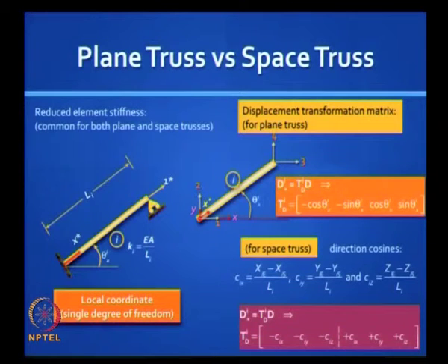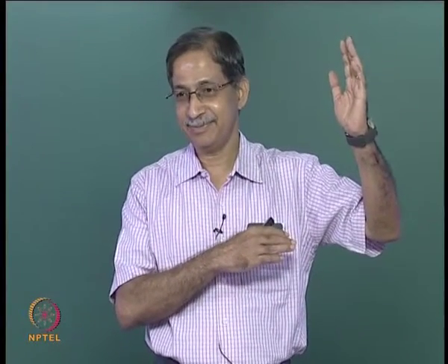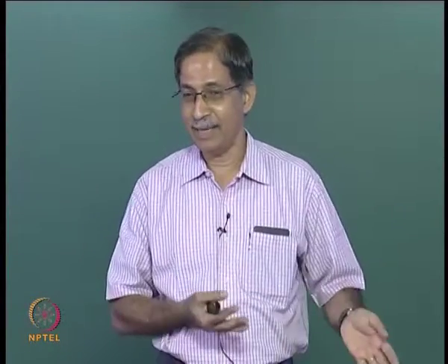That's all. Okay. So for a space truss, write down the 3 direction cosines. You don't have to write theta also. You just need the coordinates, because this is actually cos theta x, cos theta y, cos theta z. And then just like you had minus cos theta, minus sin theta, by the way, minus sin theta is actually a direction cosine with respect to the y axis. So you need the x axis, y axis and z axis, and you have minus.